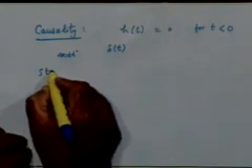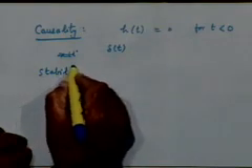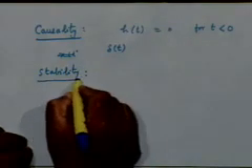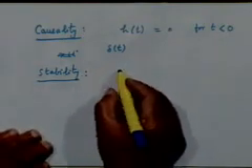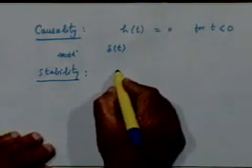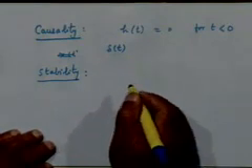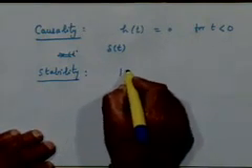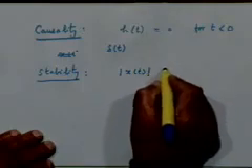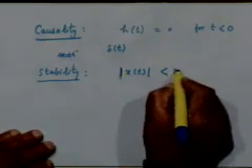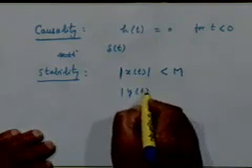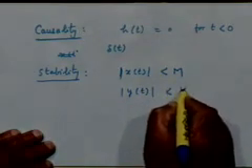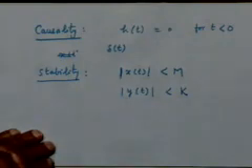Another attribute of a system which we shall assume throughout our course to be valid for the systems that we study is stability, and stability refers to the bounded input bounded output property of the system. That is, if your input x(t) is always guaranteed to be less than a certain finite value, then the output y(t) will also be guaranteed to be less than some constant value k.